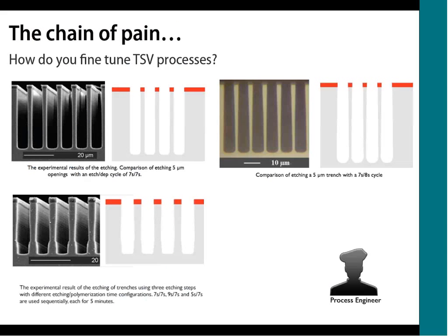And as I mentioned before, we also have some dry etch simulation tools where users can look at RIE and DRIE and different phenomena like etch lag and scalloping, and modify how the different dry etch parameters will affect the final geometry of the structures.